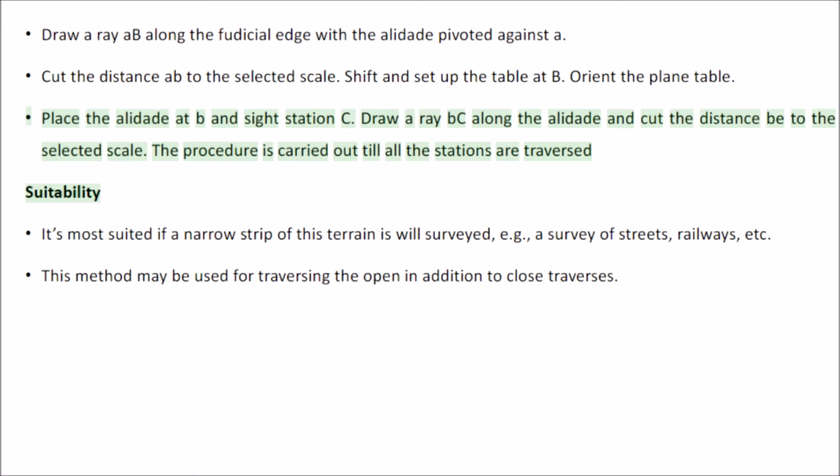Suitability. It's most suited if a narrow strip of terrain is to be surveyed, for example, a survey of streets, railways, etc. This method may be used for traversing open as well as closed traverses.